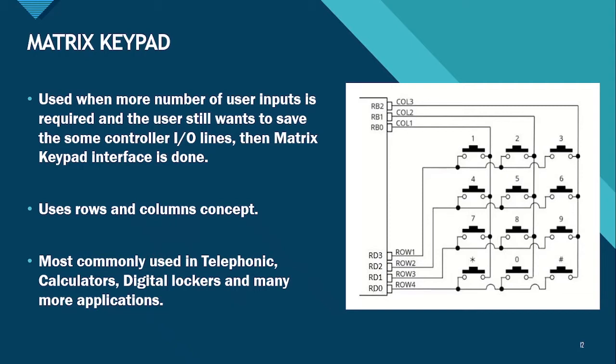Okay. The microcontroller sets all the column and row lines to input. Now, the microcontroller sets the four row lines to low, that is ground. After that, it checks the column lines one at a time. If the column connection stays high, the button on the row has not been pressed. If it goes low, the microcontroller knows which row has been set low and which column has gone low. Finally, it knows which button has been pressed, corresponding to the detected row and column, so that the input is passed to the code.